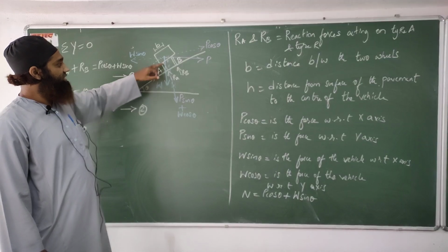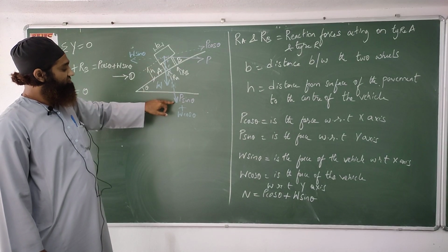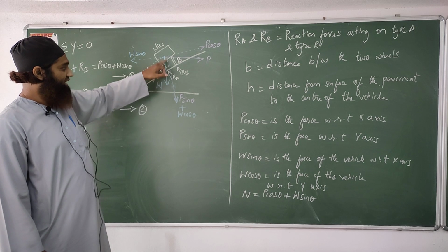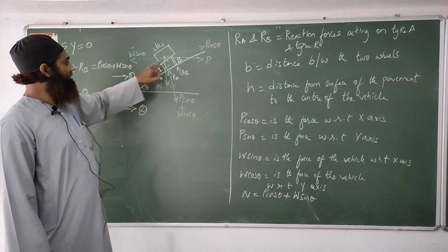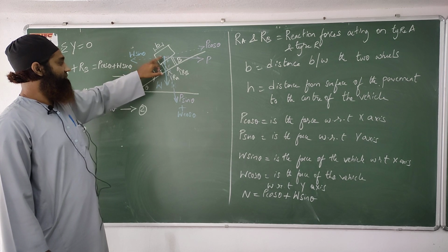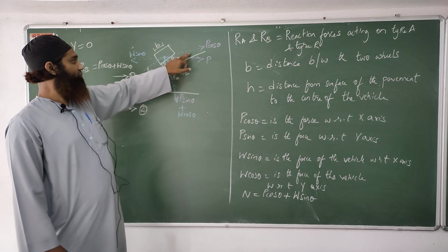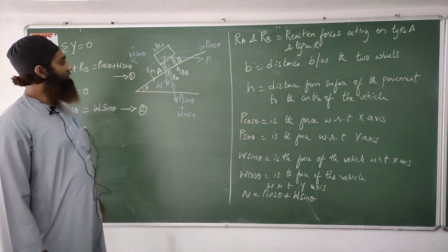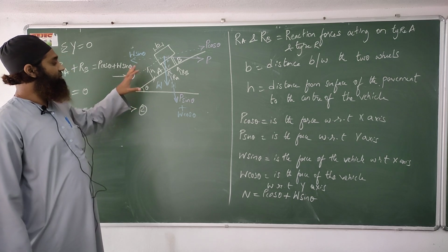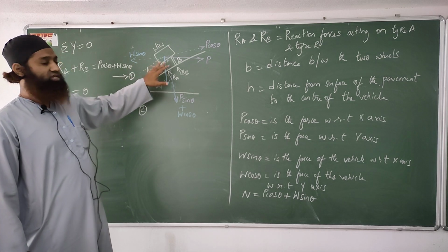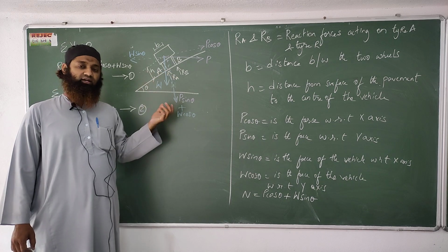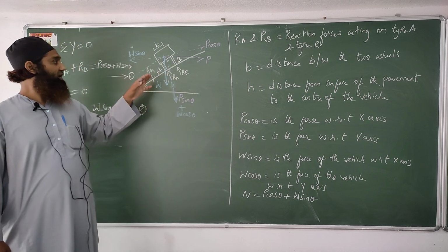You can see here, we have one force of P sin theta plus W cos theta acting downwards with respect to B. We have one force W sin theta, and we have to see the perpendicular distance. We have one more force of P cos theta, and we'll see its perpendicular distance. We'll specifically write these forces acting with respect to tire B. Then we'll equate it and we'll get a solution. Let us see that here.